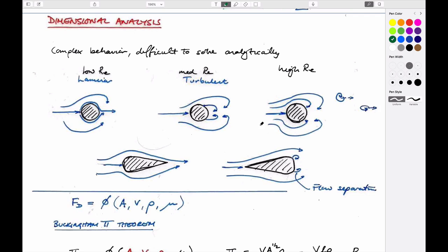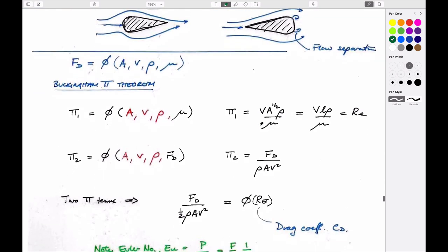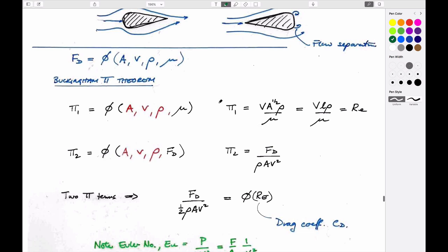The two critical properties you could get from Buckingham pi theory just as easily as what we've done here, to figure out these controlling parameters. If you do it for something like a sphere that has a sectional area, a flow velocity, a density of the fluid, and the viscosity, which includes all the components of behavior, clearly pressure drag is a function of density. If you double the density, you double the pressure drag at any given velocity because you have more mass per unit volume. And viscosity defines the shear drag, the viscous drag.